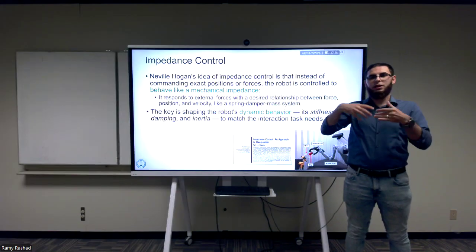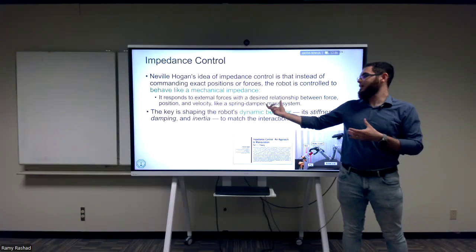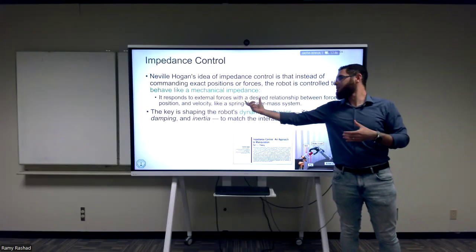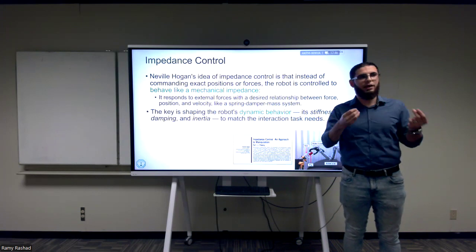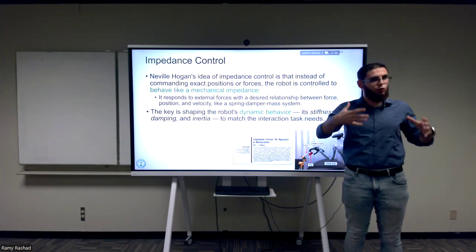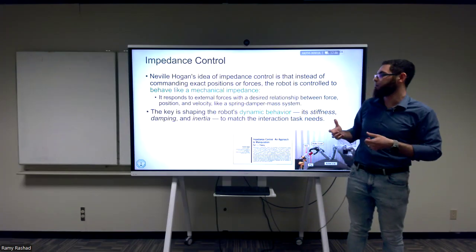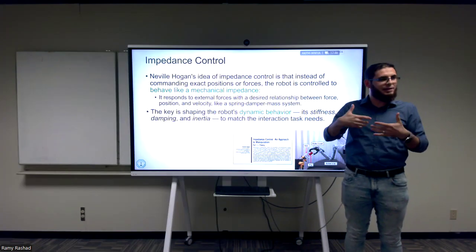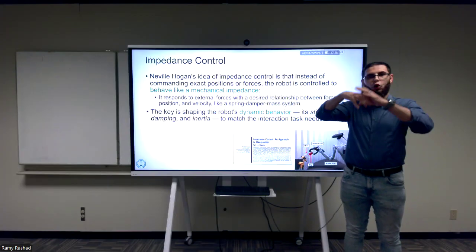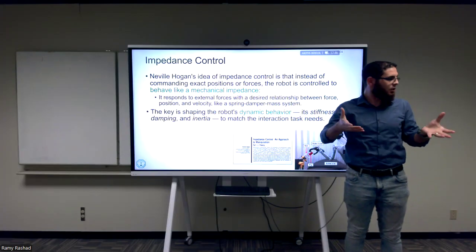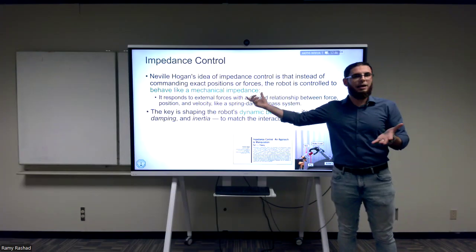And then we choose these parameters, the spring and the damper. And here, the spring and the damper will actually be controlled. So there will be a virtual spring and a virtual damper inside of the controller itself. It will behave as if it's a spring and a damper. So the controller will behave as if it's simulating a spring and a damper in the real system. And the overall closed loop system, which is the robot plus the controller, will behave as a mass-spring-damper system.